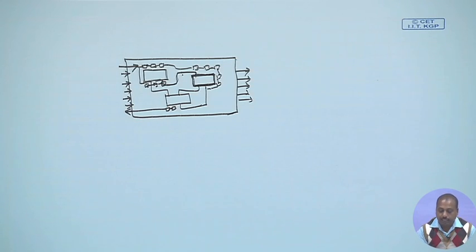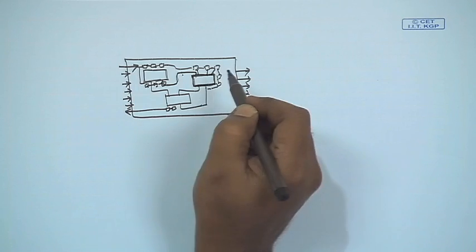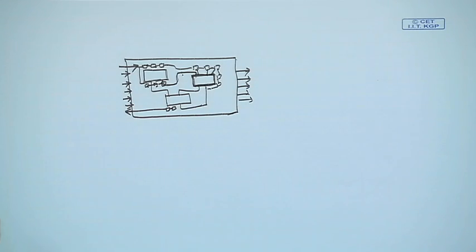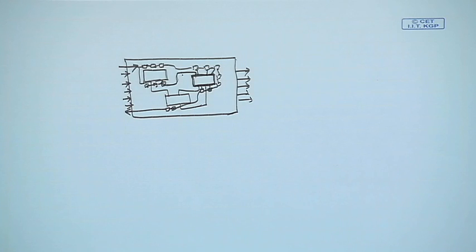What is happening is that we can pass any pattern into this chain, and we can say after how many shifts the pattern will reach the particular chip input, and that way these inputs can be fed to this chip. Similarly, the responses from the chip can also be collected, and they are ultimately connected to this chain. This way we have a very elegant way of testing the chips without taking them out of the board. If it is an automated process, it will send the patterns to the individual chips without taking them out of the board, so the testing becomes easy.